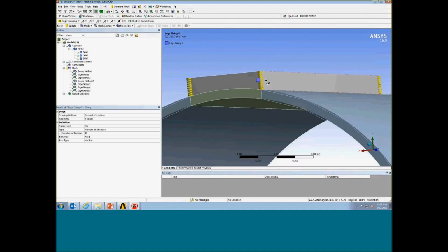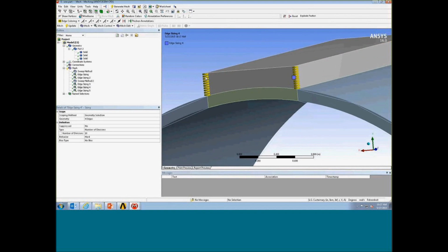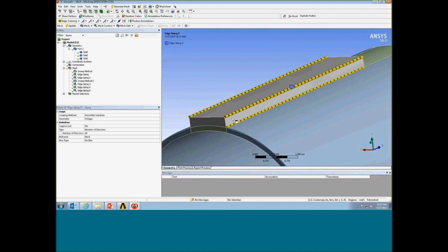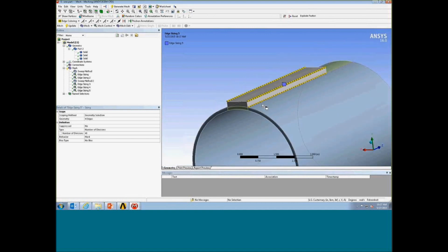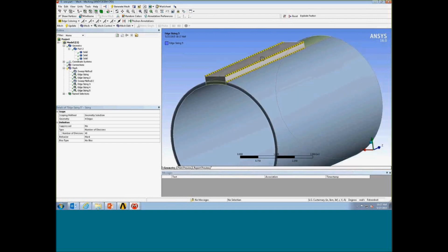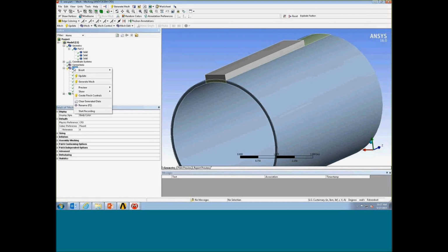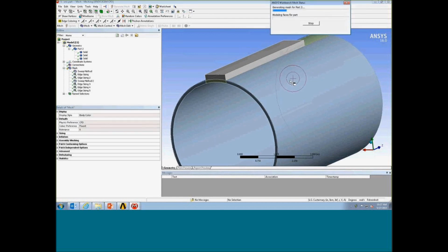And I have the number of elements that I want in the cavity region. And lastly, I have the number of axial elements in the cavity region. So all I did is just divide the flow domain into 3 pieces, and because now they're all sweepable, I define for each region, each edge and each line, what element sizing I want and how many divisions I want. I can control this precisely, and right-click, say Generate Mesh.